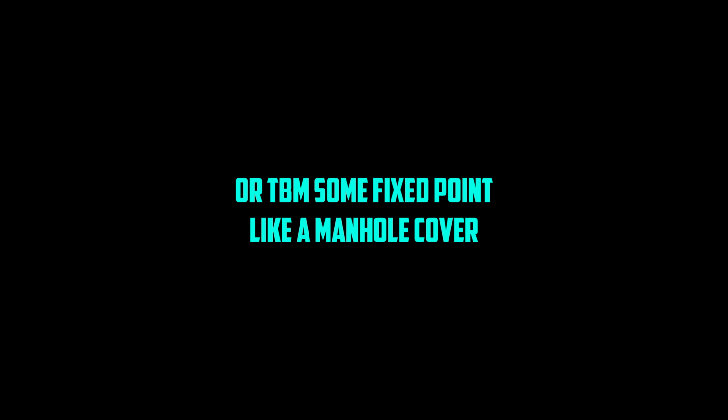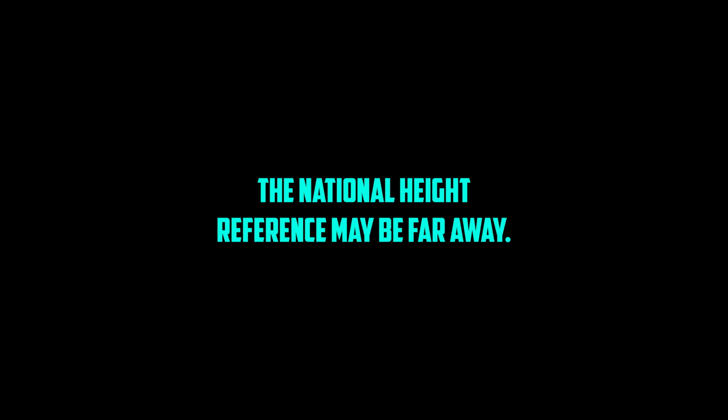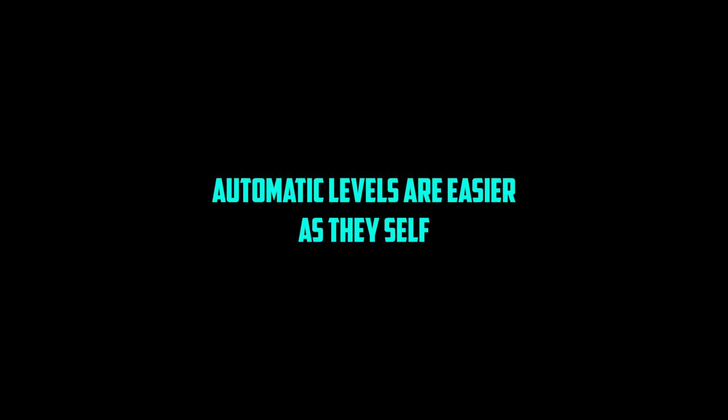And getting the levels, the heights, right, is obviously crucial for all this. Absolutely fundamental. On-site, you usually work from a temporary benchmark or TBM, some fixed point, like a manhole cover, because the official ordnance datum, the national height reference, may be far away. You use leveling instruments like tilting levels or, more commonly now, automatic levels with a measuring staff. Automatic levels are easier as they self-level internally.